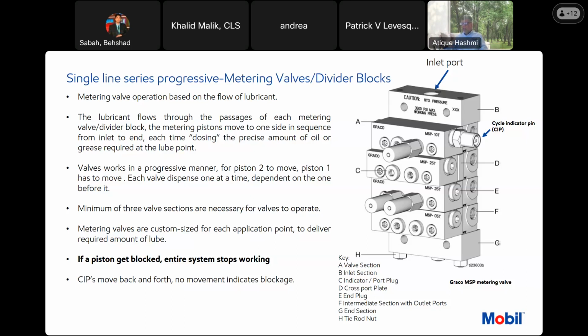Then we will collect the information on the bearings, like the size of the bearings, the speed (RPM), the temperature, all those things. Then we will run calculations on the bearings just to identify how much grease is required by one bearing per 8 hours.